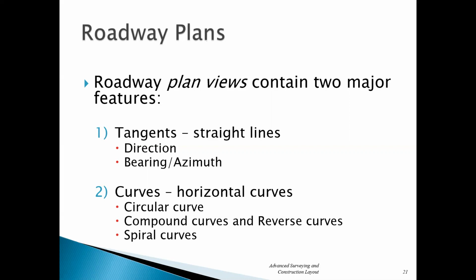The other kinds of curves you would have in highways would be compound curves and reverse curves, or spirals. Compounds and reverses get much more involved, and spirals geometrically are probably your most involved type of curve. In any highway you drive over around here, you're using circular curves for part of those highways and spirals for the other part.